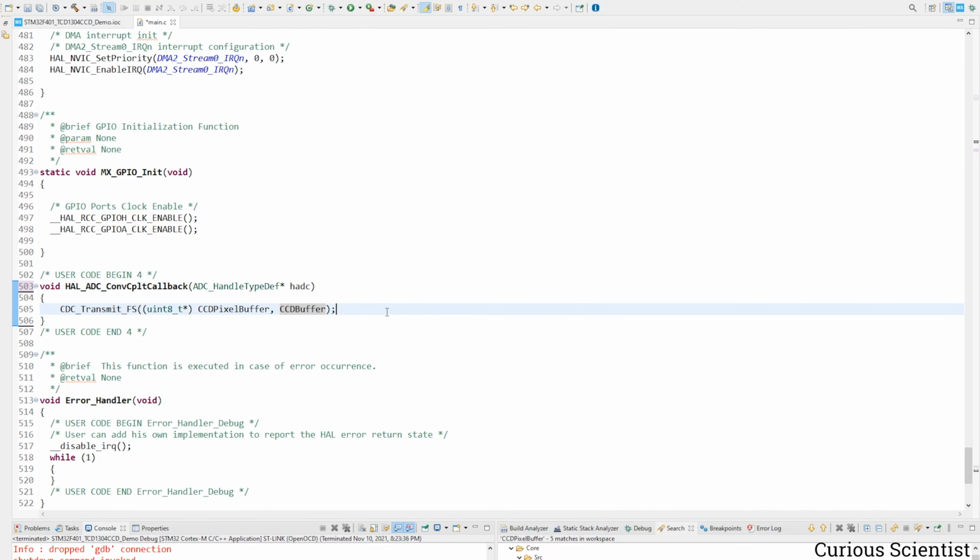So in fact, when you check the output data of the ADC on the USB, you will see a bunch of random characters because you get the binary data. And it's not enough that it is binary, but it is split into two parts, two 8-bit numbers. So on the receiving side, you actually have to capture this data carefully and then combine two adjacent numbers, pairs.